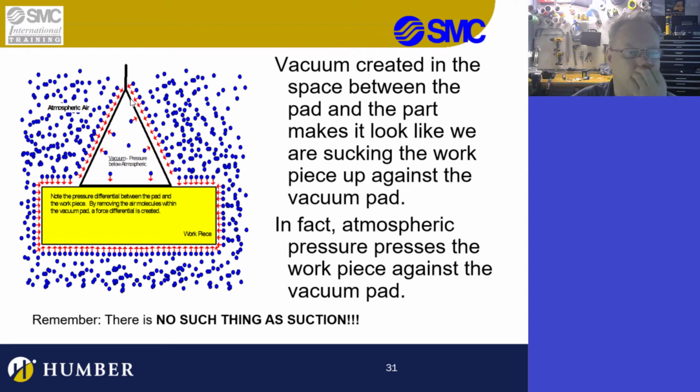Okay, here we go. This is just the example here. This goes back to how vacuum actually works. It's the differential pressure between the atmosphere and the vacuum inside. So the thing that's clamping the part to your suction cup is the differential pressure. It's the vacuum inside and the air pressure pushing. So it's kind of like if you lift something up, the air pressure's pushing it up. Not really, but kind of. I mean, there's actually a robot or a machine or a cable or a mechanism physically doing the work to pick it up.